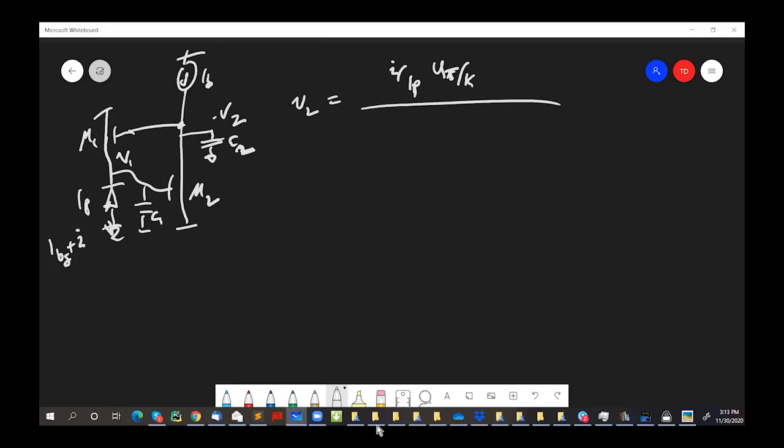And then in the bottom, we had this expression for the transfer function that was like tau 1 tau 2 S squared plus tau 1 plus tau 2 S plus 1, only there was a kappa A here, right? Where A was the gain of this amplifier.